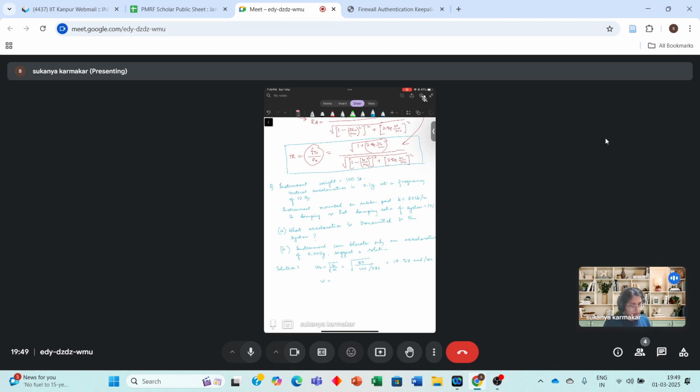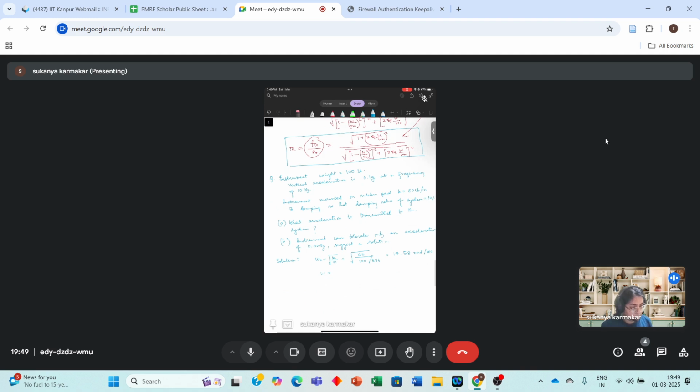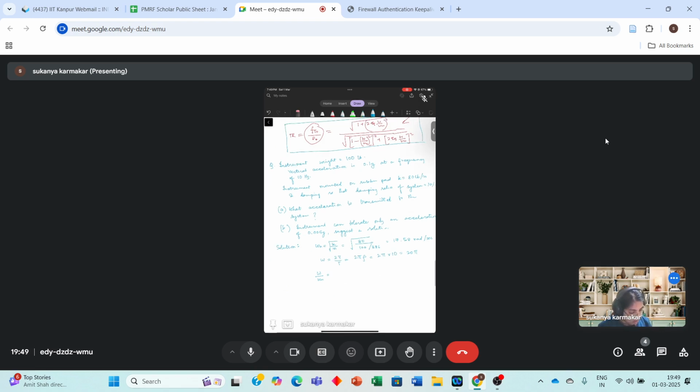Now you know omega n, and you have what is omega. It is given that it is at a frequency of 10 hertz. So if you convert it, omega is 2 pi by time period, and 1 by time period is frequency, and frequency is 10 hertz. So 2 pi into 10, so 20 pi. So omega by omega n, you can simply calculate 20 pi by 17.58. This comes out to be 3.575.